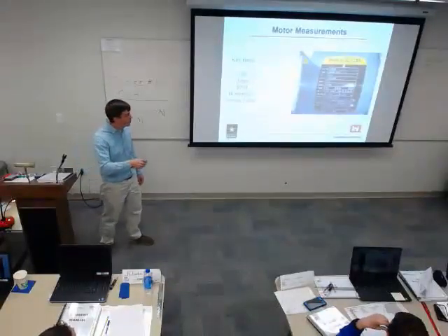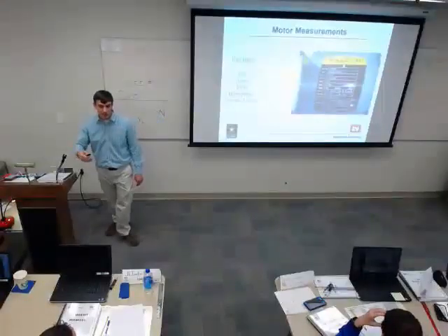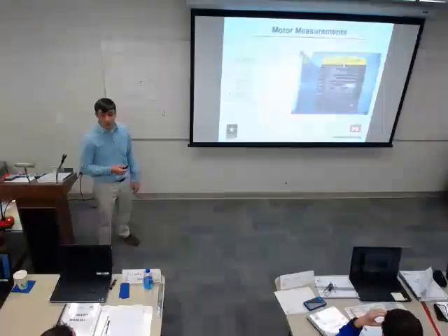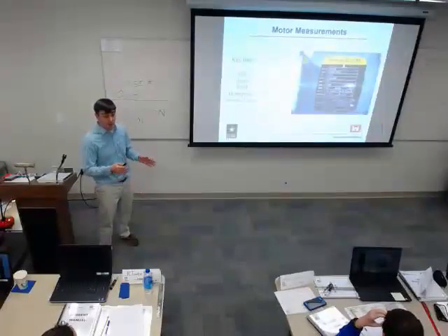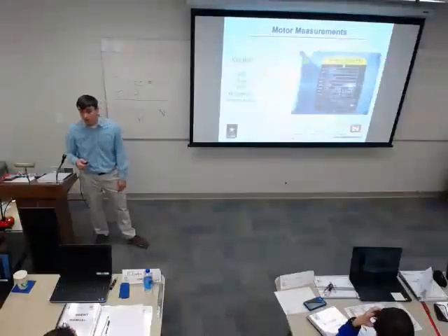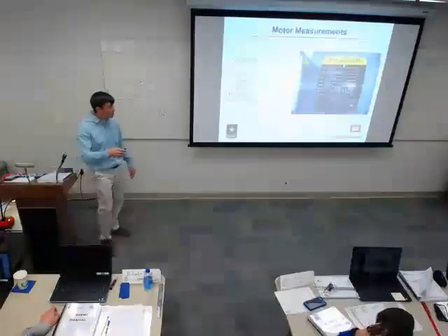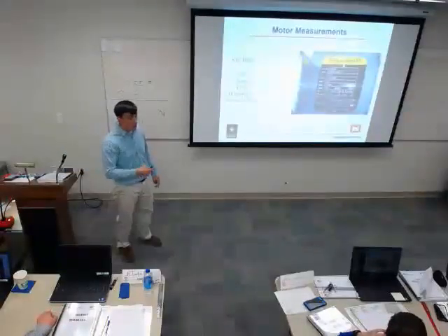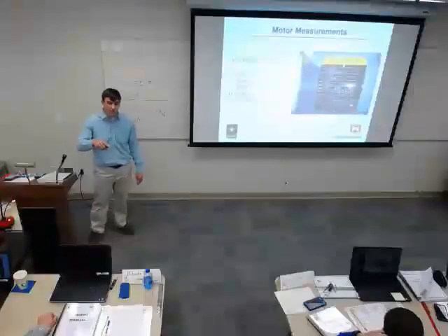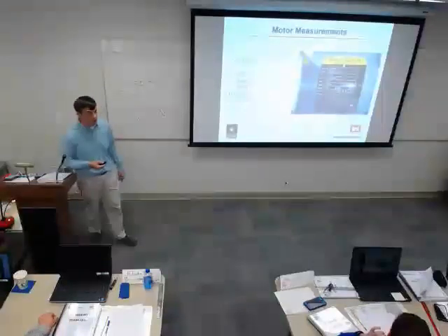If you read the NEMA standard for motors, it'll tell you don't exceed it permanently, but it's okay short term. So it allows for problems on your distribution system, basically changes in voltage from phase to phase. But you should not be running a motor in its service factor permanently. It will decrease the life of the motor. The NEMA MG1 standard, which all the motor manufacturers build their motors to, says that. If you've got a contractor arguing with you, pull up the NEMA standard for motors and show them that paragraph. I think it even says it in A and B, C as well.